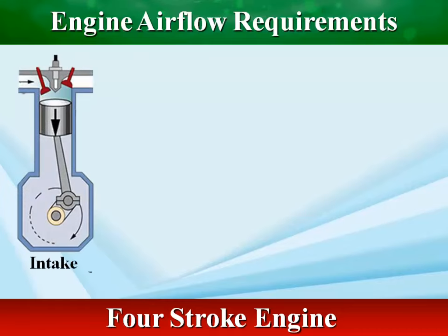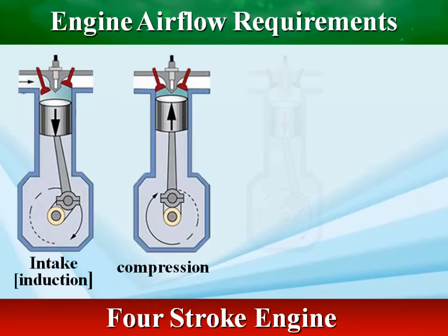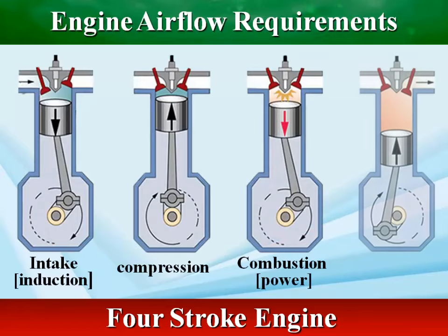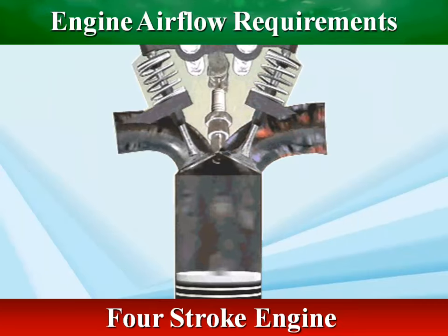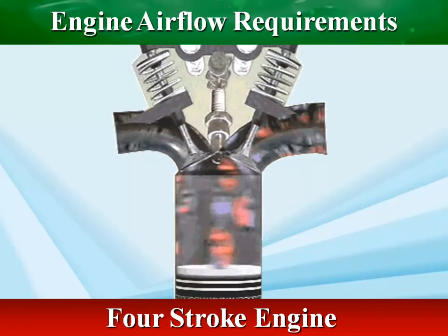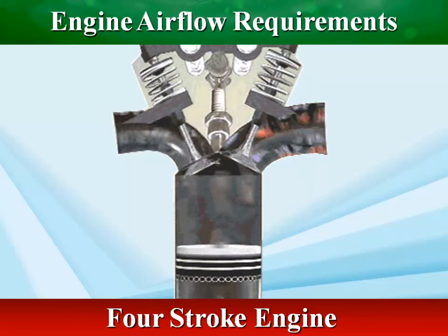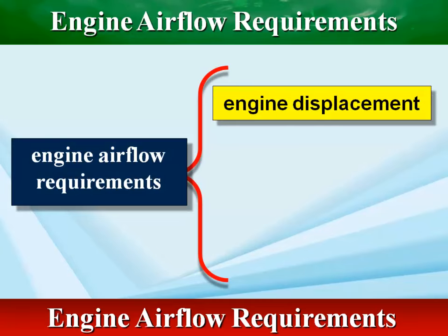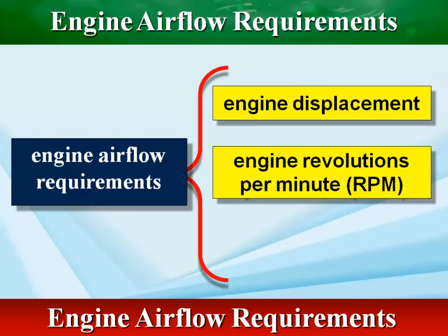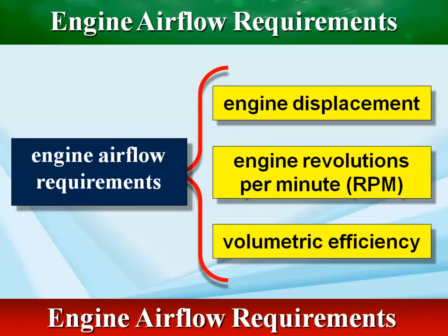A 4-stroke engine can take in only so much air. The amount of fuel it needs for proper combustion depends on how much air it takes in. Engineers calculate engine airflow requirements using 3 factors: engine displacement, engine revolutions per minute (RPM), and volumetric efficiency.